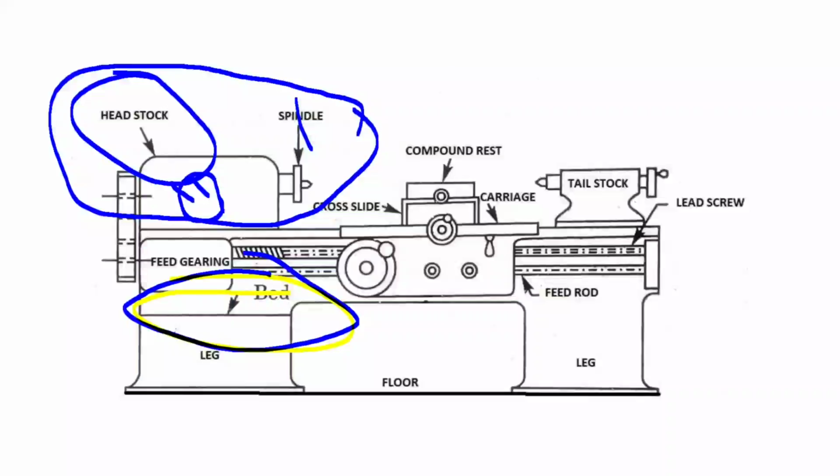Material is one of the important things which can change your speed, the tool, and many things. Then the second is the type of cutting tool material. Then the type of finishing required. Then comes the type of cutting fluid used, rigidity and condition of machining, the diameter of the workpiece, and the type of operations.